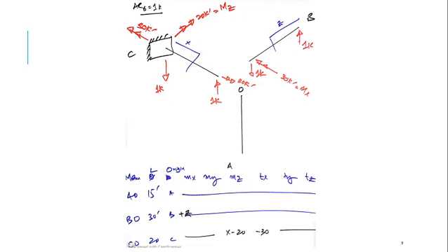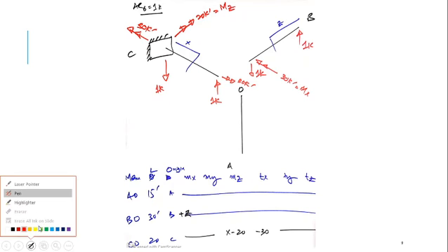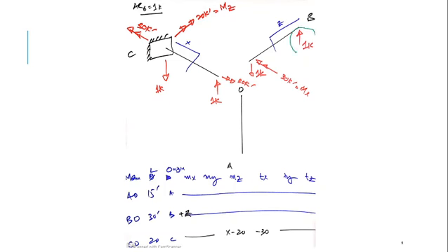You know AR6 is a vertical load here, so 1 kip is now balanced with this 1 kip. This will be balanced here with 1 kip, because I have to balance this joint O. Again, you should know that this 1 kip is in Y direction and this member is in Z direction. So if loading is in Y and the member is in Z direction, there would be a moment in X direction.